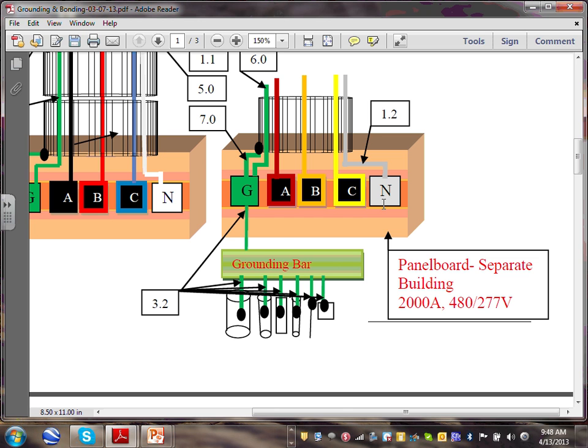You're trenching, and you're going to put a cable. You put the 5-conductor cable. So really, that exception is almost not meant to be used. The only thing I can think of is the farms. On the farms, they use a lot of that one. But anything new, if you pull your conductor, you have an equivalent conductor with it.